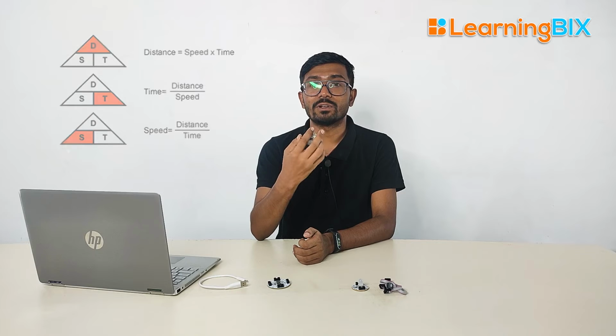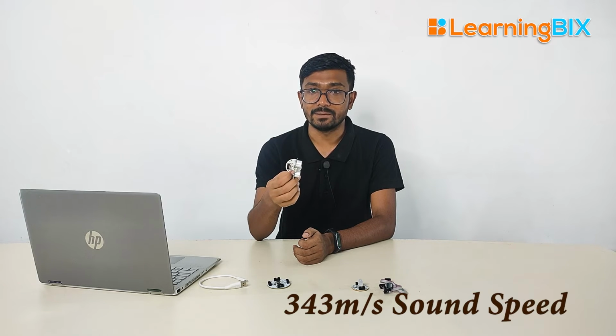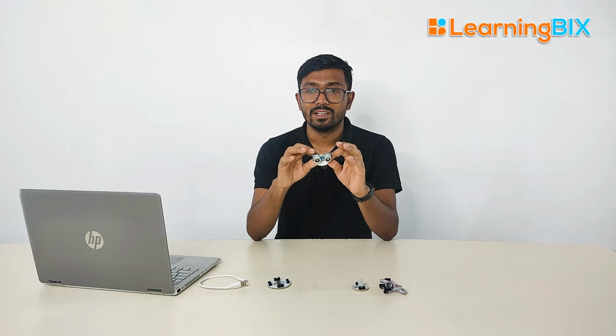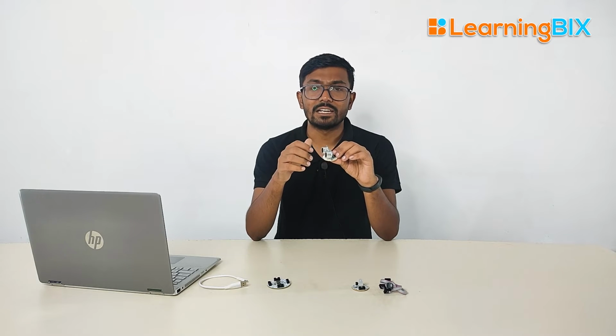For speed, we have the speed of ultrasonic waves in air, which is 343 meters per second. In a different medium it might be different, like for water or for solid surfaces, but for air we are measuring it. For the current purpose we are going to use air, that's why we need 340 meters per second. So we have the speed. Now let's see what the time is, or how we can calculate the time.